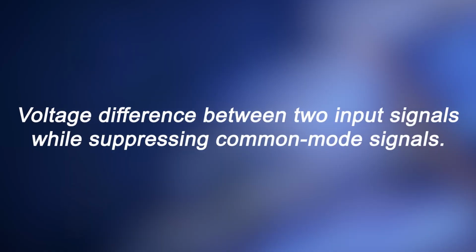In this lecture, we will discuss the basics of differential amplifier. A differential amplifier amplifies the voltage difference between two input signals while suppressing common mode signals. The output voltage V out is proportional to the voltage difference between the inputs scaled by the amplifier's gain.